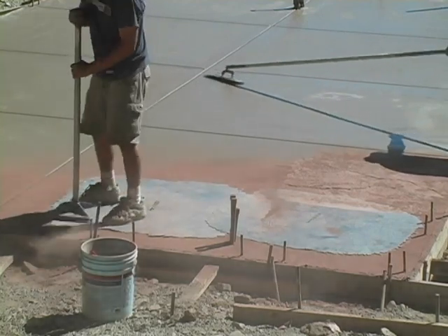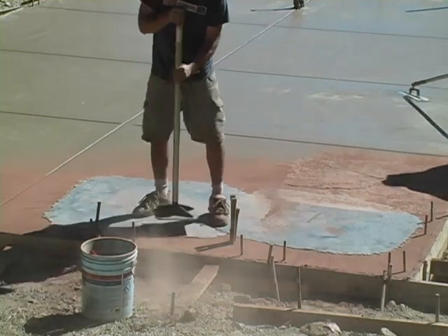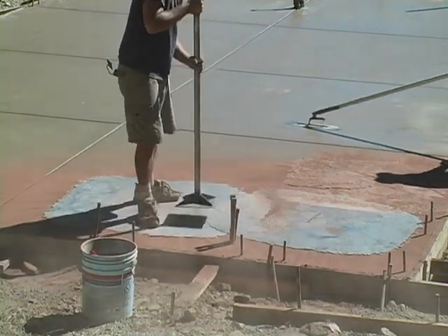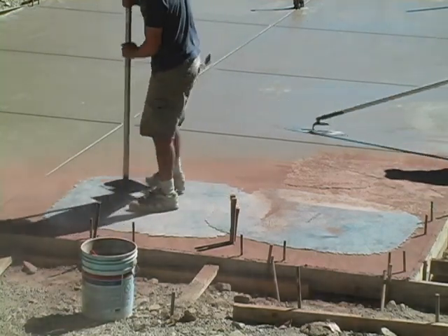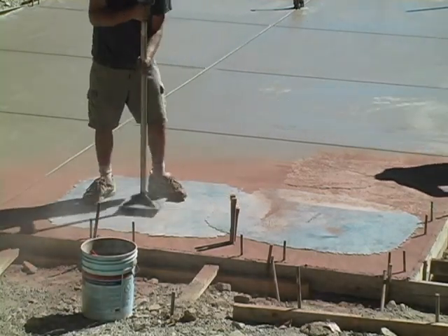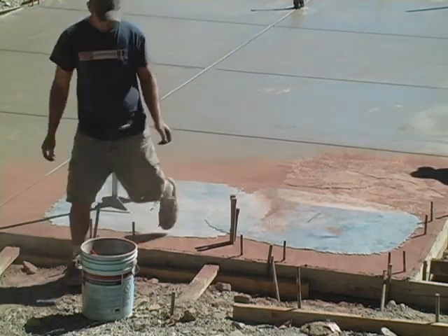And again, don't forget to have someone in the background working the concrete to keep that open film. You can see areas where it was drying right there where he just slid over. We're keeping that active and keeping the concrete pliable so we can do the stamping process. We've got a long way to go before we get around this whole building.